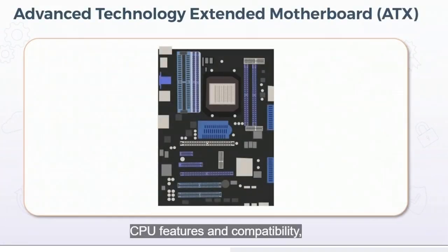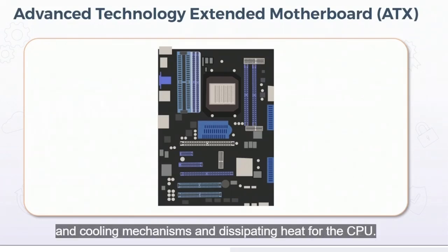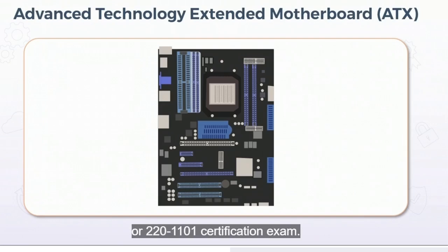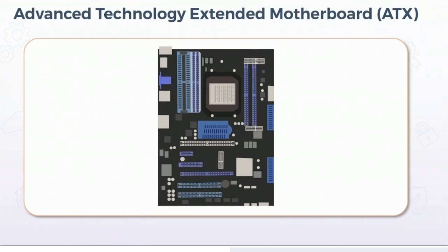Now, this is a general idea of the overall shape and appearance of a typical ATX board from the perspective of the left side being the back of the computer where all peripheral devices were attached. So the beige square in the upper center would be the socket where the processor was installed, and the darker purple slots in the upper right were for the system memory, or RAM. And that's actually important because they were placed there intentionally because it lined up with the fan output from your power supply, which provided inherent cooling across both the processor and the memory. And since it was a standard size, it would fit into any ATX case, regardless of the manufacturer.